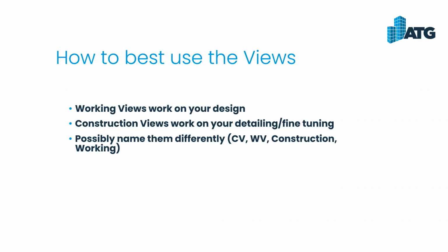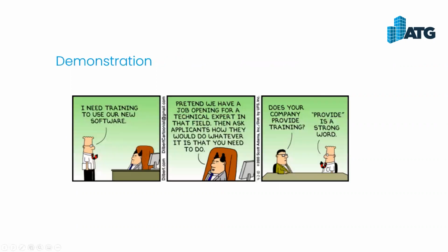Just remember, if you are doing that, as you're placing views onto sheets, you may want to rename the view in your properties. You have the option to rename the view on the sheet and take off the CV, WV, construction, or working on the back end of that. You probably don't need that showing up on your construction plans. All right, so let's pop into Revit here.